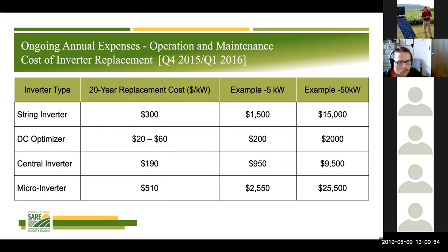So I mentioned earlier that we looked at how we model the O&M cost, and historically we've used, say, $15 per kW annually. One of the things that I'm questioning is if we could do that a little bit better. Given that inverters are such a large component of that O&M breakdown, maybe we reduce that $15 and say instead we apply $7 to $5 per kW annually.